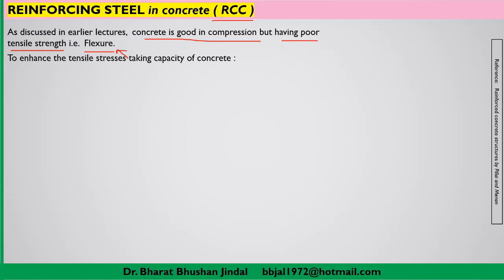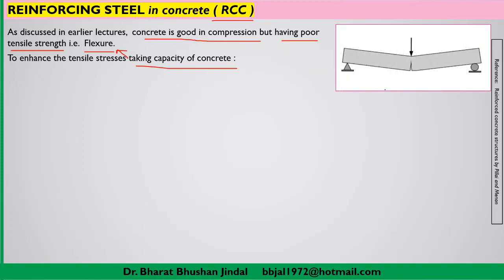Now, what do we do to enhance the tensile stress carrying capacity of concrete? You can see here in the figure. In figure A, there is a simply supported beam member, and when it is under flexure you will find some flexural cracks.